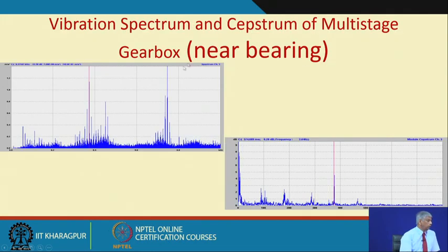Now you see this is the vibration spectrum here, and you see there are so many side bands of this multistage gearbox. But if I do this Cepstrum, I will see a peak, and this value in the time domain actually corresponds to the frequency of rotation of that particular gear near that bearing. Because, let me tell you, particularly in CBM, as you will see later on,